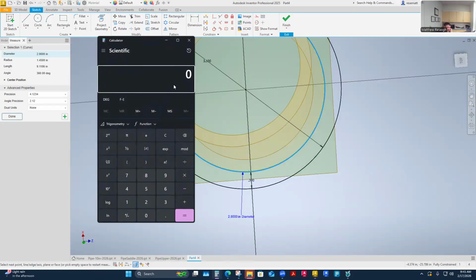So I might do a little check here. 2.9 on the inside diameter of schedule 80 3-inch pipe, and then if I subtract 2.875, I really have only 25 thousandths. I need to divide that by 2 to see the all-the-way-around clearance, and I'd have about 12.5 thousandths. It's probably a pretty good fit, way less than an eighth of an inch, which is 0.0625. It's pretty tight though.